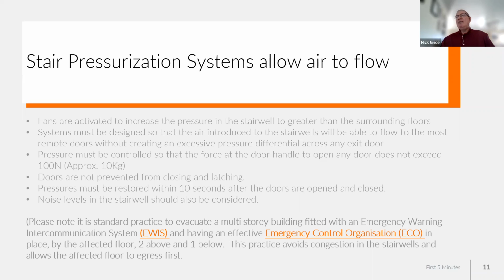Noise levels are a factor and should be considered, especially when you're doing training in high-rise buildings. But you say, don't worry about the noise in the stairwell. It does get very noisy. These pressurization fans, in a high-rise building, you might have a fan on the roof, then you might have another fan about 4 or 5 floors down, and then another fan about another 4 or 5 floors down. So quite a few fans going on. So just make sure you know, if you're doing training in buildings, that pressurization fans is quite a natural thing to occur.